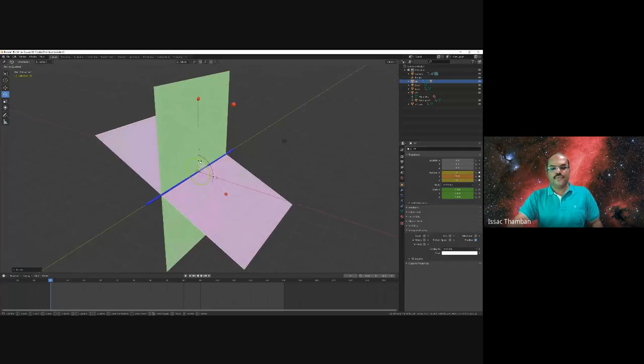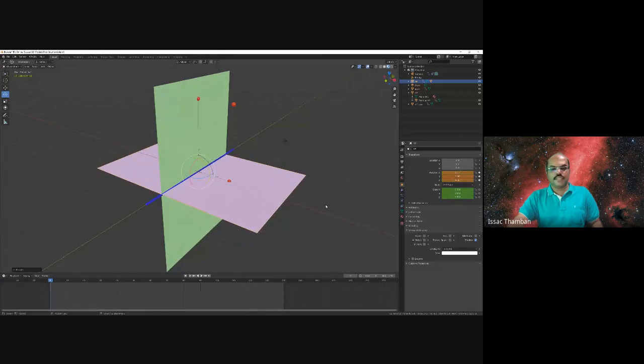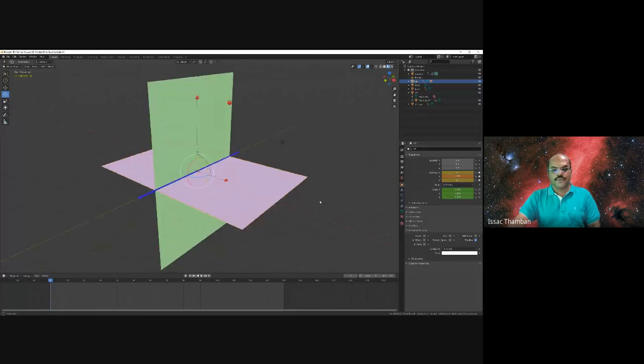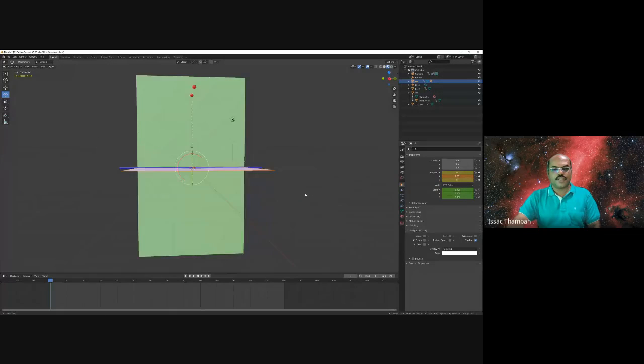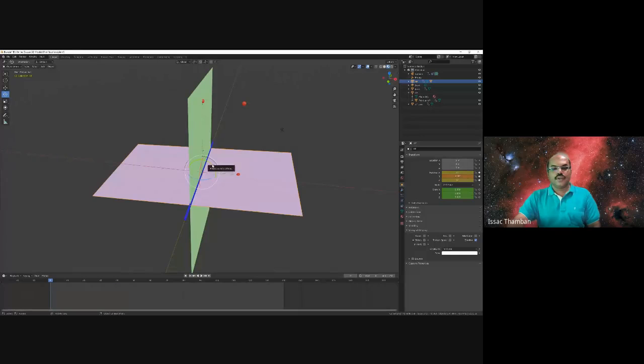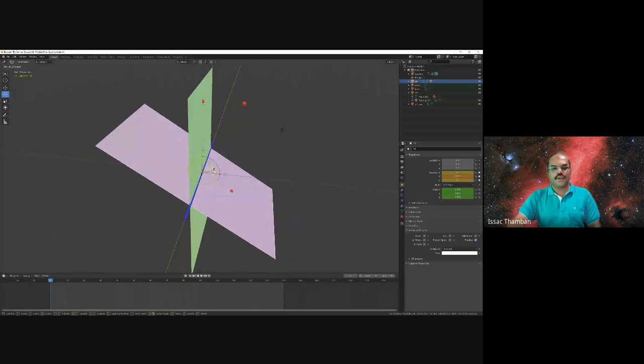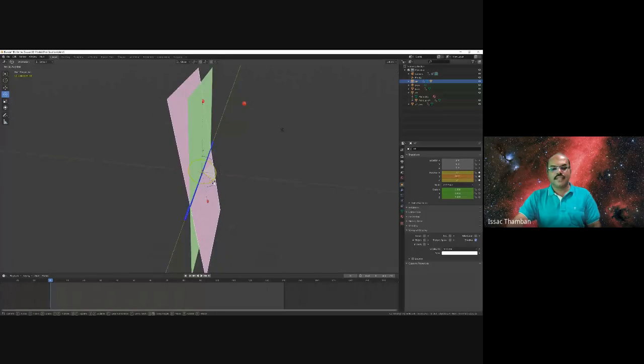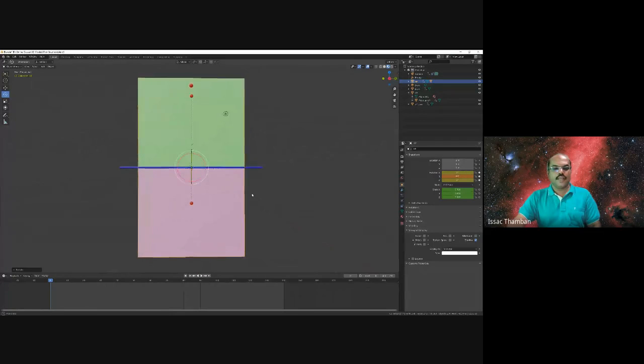You are looking from this direction. And you have to tilt the reference plane like this to obtain the projection that can be represented over the drawing sheet. So, placing like this, and I am looking in this direction so that I will get a projection like this. This is our elevation and this is our plan.